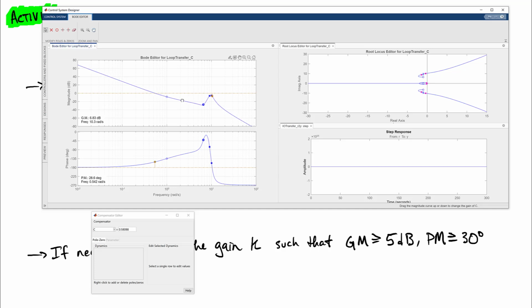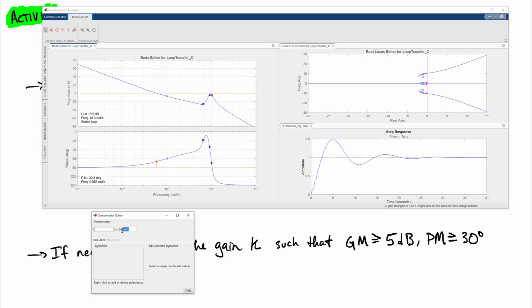And so what we need to do is identify, so now we're below 30 if I keep pulling this down, decreasing it. So what it says is that increasing the phase margin for a little while at least is good for this system. And so if I move this up a little bit more, let's call it right there. All right, that's 30.5 degrees phase margin, so right around there. So as long as the gain is bigger than 0.67, then we will achieve our phase margin.